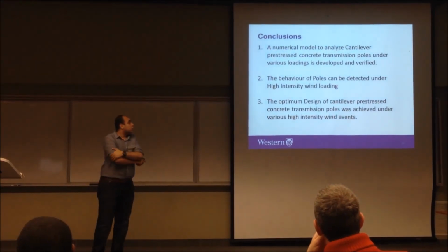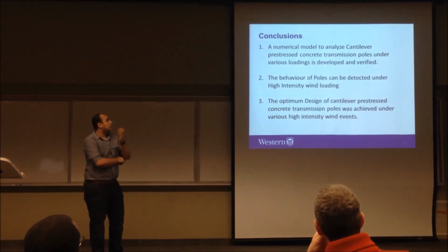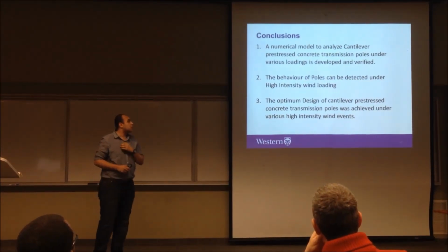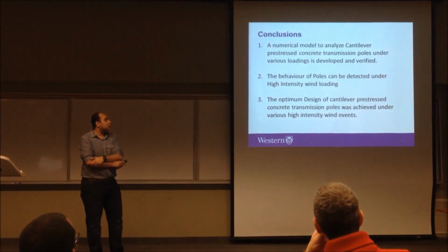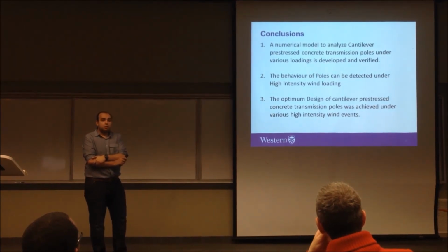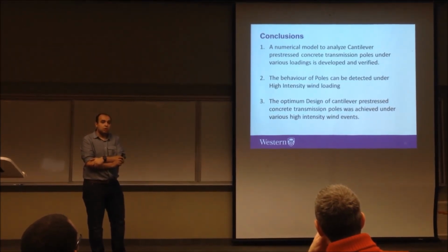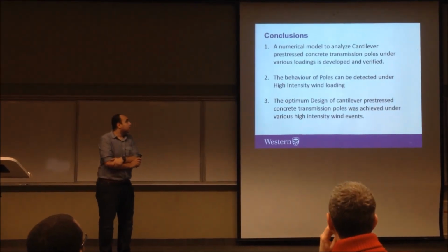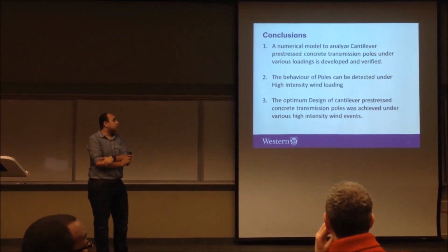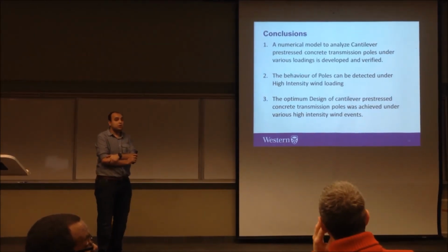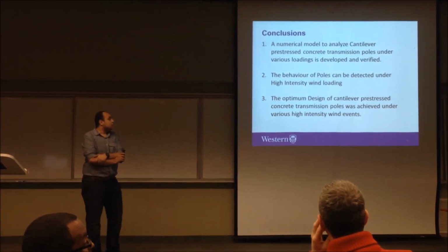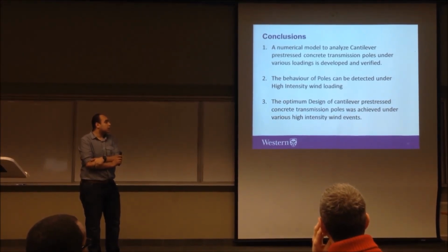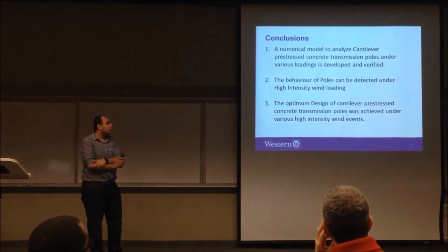The conclusion of the study is that we have reached a numerical model to analyze cantilever pre-stressed concrete transmission poles under various loadings, and it was verified with the load test that was conducted by Fayed et al. in 1994. The behavior of the pole can be detected under various high-intensity wind loadings, and the optimal design of cantilever pre-stressed concrete transmission poles was achieved under various high-intensity wind events.